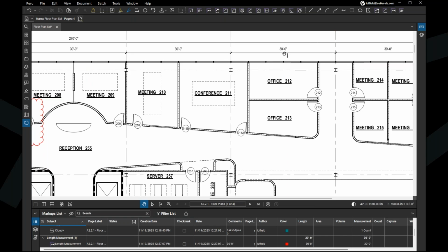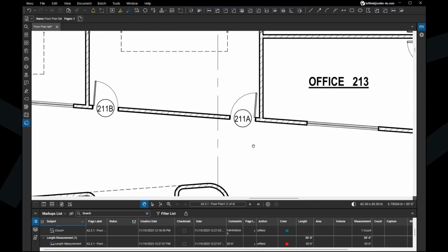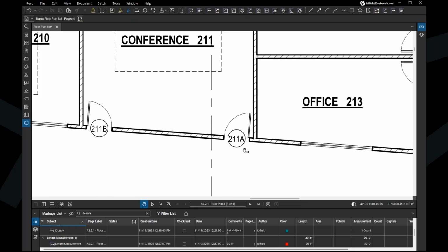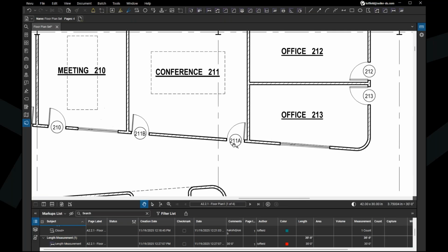Maybe you're looking at a drawing that doesn't have any measurements provided on the page. That can certainly happen. You can use a known width of any kind, like let's say that these are common door frames. That's 36 inches. I could calibrate from one corner here to the other corner at 36 inches and apply that scale there.